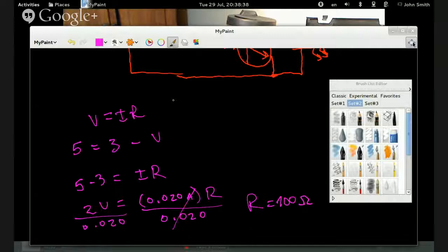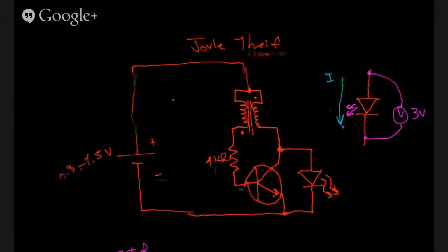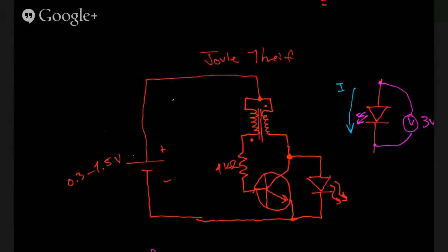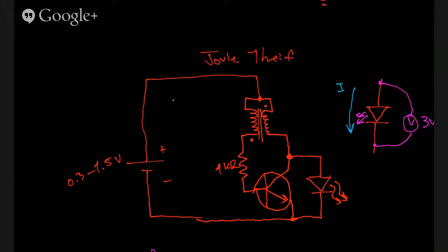I'll explain how a Joule Thief works. So here's our battery, right? So this is a transformer. It's basically we got a wire, this wire around here, and this wire is in the opposite way. It's in parallel, right? And they're both coupled by a donut shape, toroid. Alright? What a toroid does is, remember that a coil, it would probably help if I had the microphone over here.